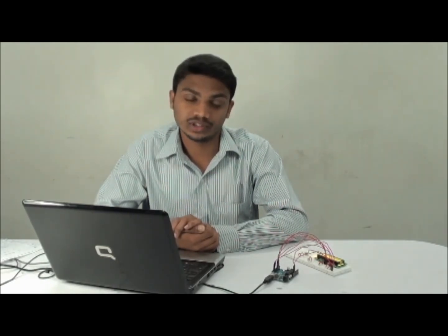In this video, I am going to explain the 16x2 LCD display, its working, and its hardware inside. These display devices are used to display characters as well as digits. The 16x2 means it can display 16 characters in each line, and there are 2 such lines. This LCD display uses the very popular HD44780 parallel interface chipset. These LCD displays come in 16 pin packages, and let's see its pin configuration.